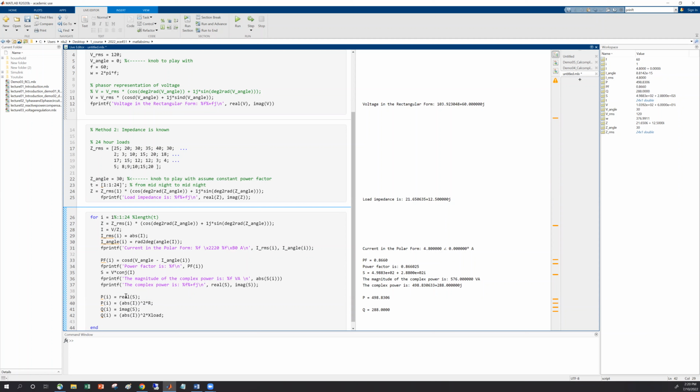So similarly, a sine wave of I can be equivalent to a DC I. So when you compute the power consumed, you can think of this value as just using the absolute value of I squared, and then times this X load, and that will give you the reactive power and then the real power. Okay, so let's see if that gives us the same value.